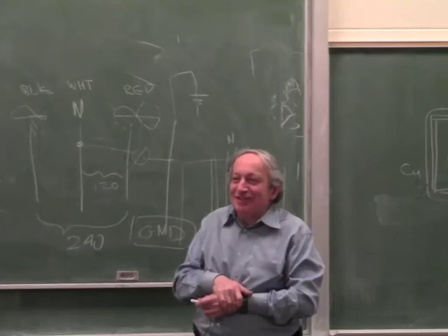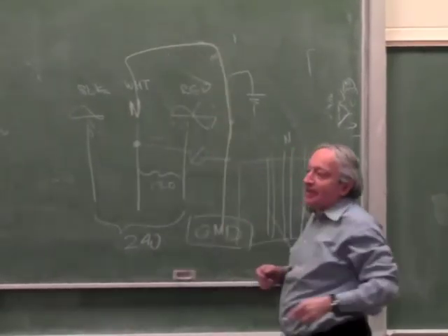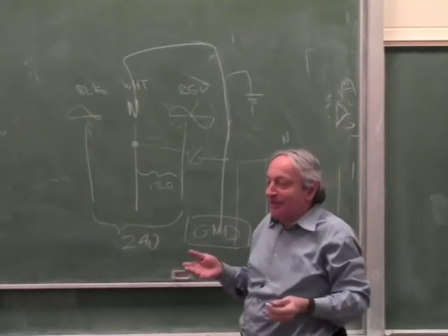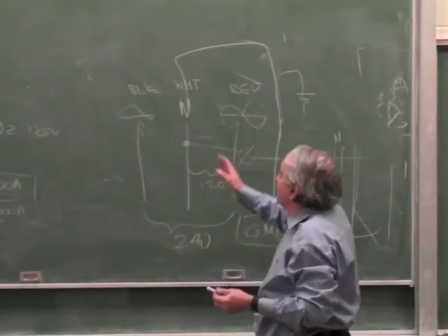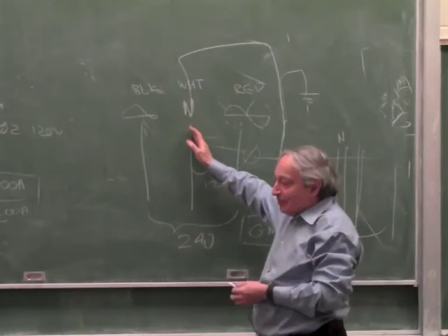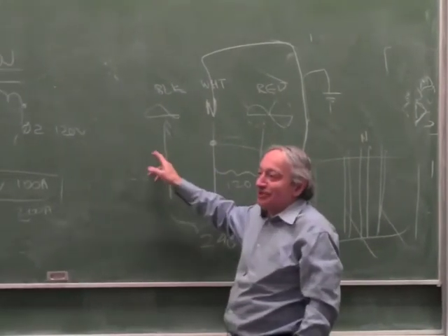It's the same story every year. Of course it's short. The neutral and ground are connected together. It's one wire outside the house. And if you ever try it, you'll see. You can try it with power on, because neutral doesn't have any power. But just to be safe, don't try it with power on, in case you plug in the ohm meter at the wrong place.